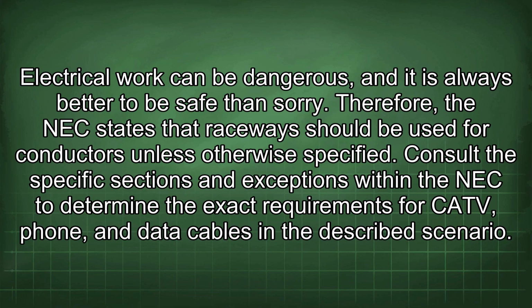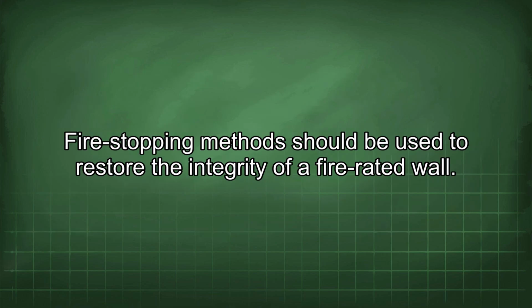Therefore, the NEC states that raceway should be used for conductors unless otherwise specified. Consult the specific sections and exceptions within the NEC to determine the exact requirements for CATV, phone, and data cables in a described scenario. Fire stopping methods should be used to restore the integrity of a fire-rated wall.